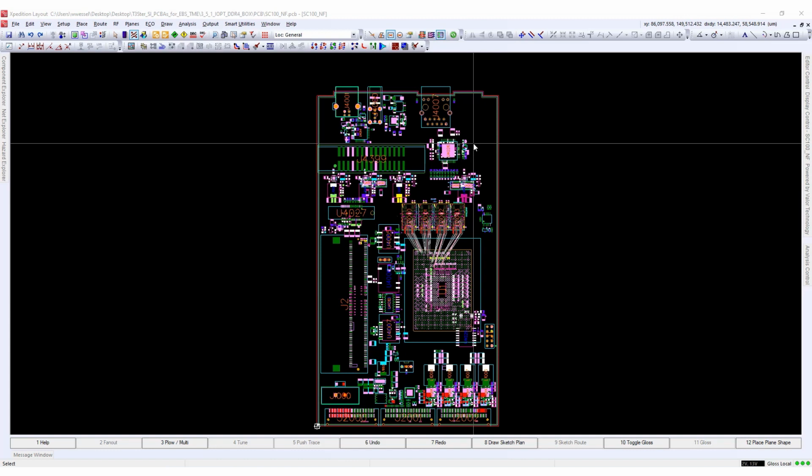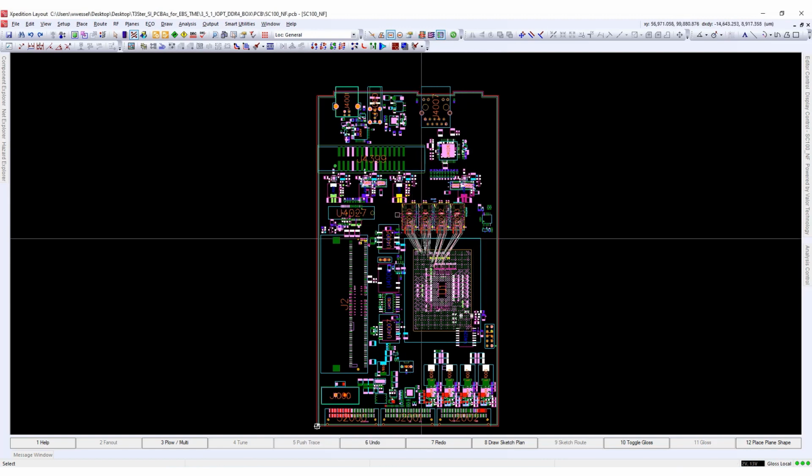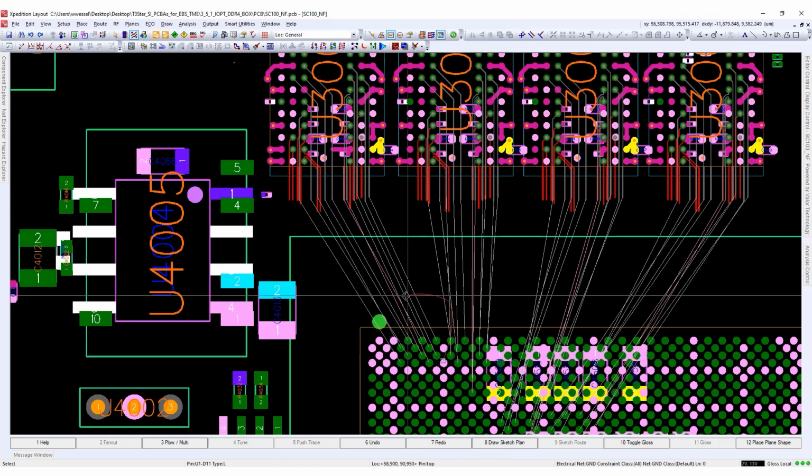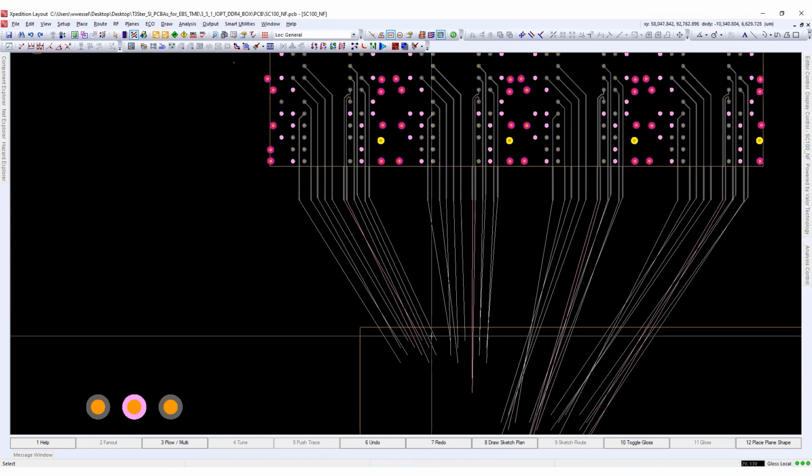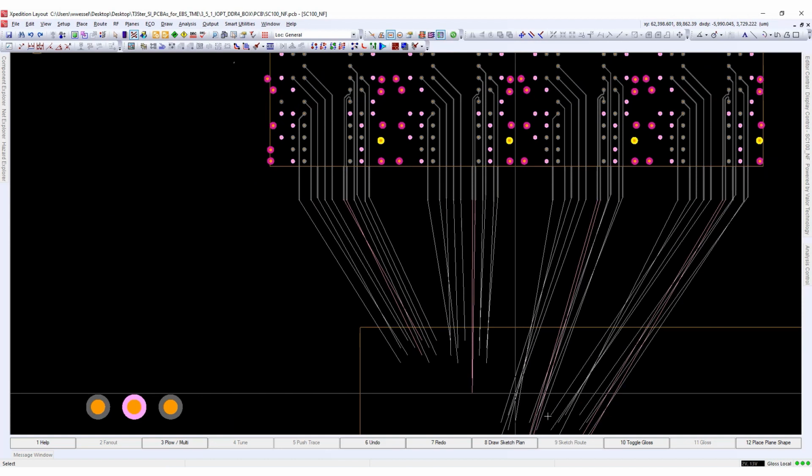We saw in the previous video that I/O Optimizer is capable of guiding during part placement and supporting the fan-out and breakout process. In this phase of the design, we are using FPGA I/O optimization to improve the pin assignment based on the pre-routed signals, taking into account the layer usage. Before we can start the second optimization run, we need to use the methods and functions shown by ZAC to complete the fan-out and breakout for all other signals.